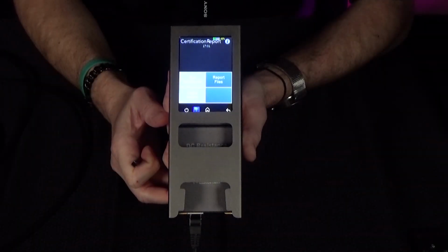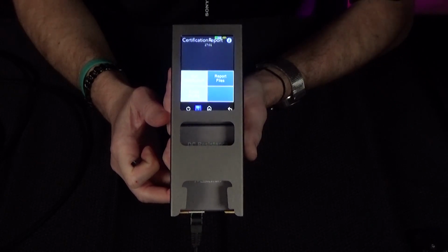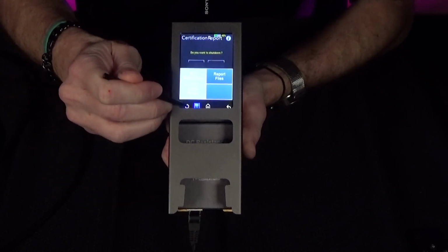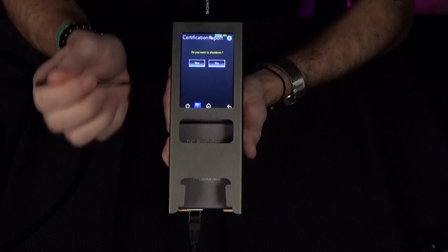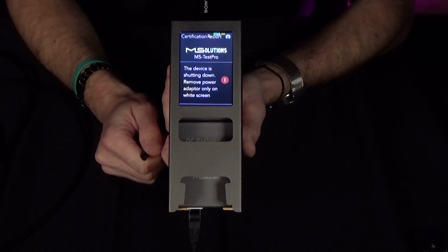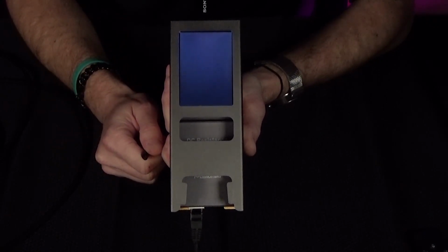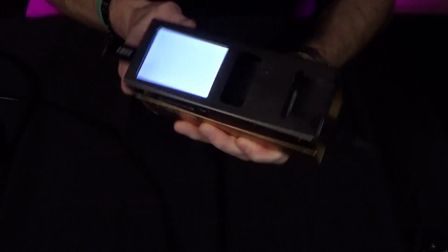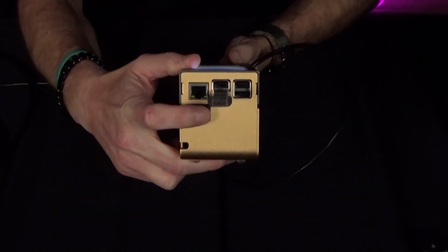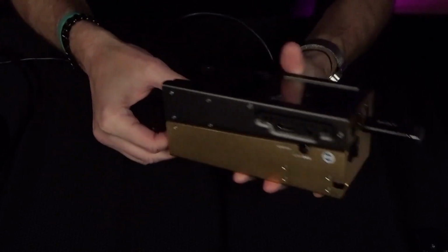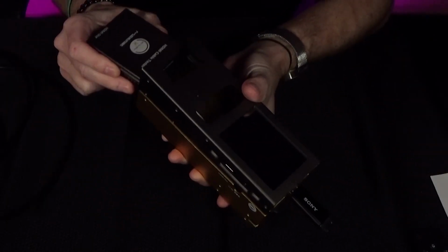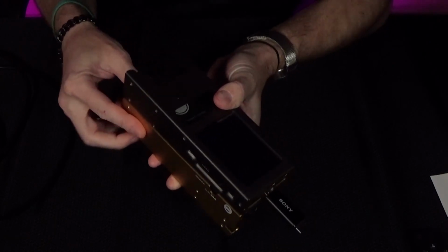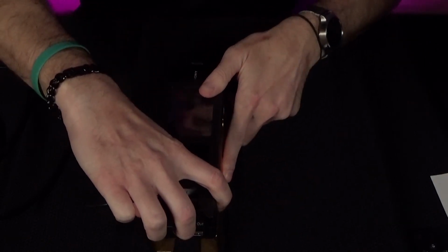Next, we'll take a look at the HDMI cable tester. Remember, if the unit is powered on still, let's go ahead and turn it off so we can install the HDMI tester module. Now that the screen is white, we can turn off the main power switch, remove the current module, and install the HDMI cable tester module. For this test, we're also going to need the looper module.